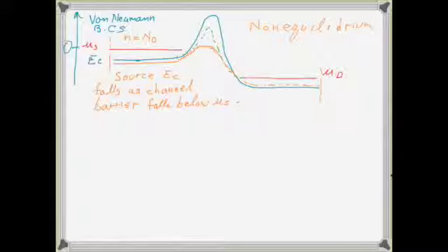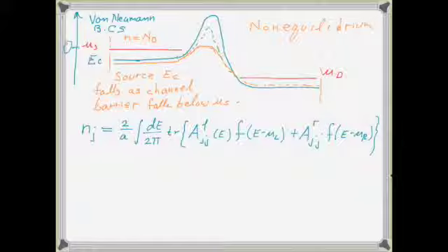To understand what happens, we need to go back and look at the equations that we use to get the charge density. That's the expression for the non-equilibrium charge density. For any normal FET, this difference here, q VDD, is at least 0.4 volts or more. Even 0.3 volts, it doesn't matter. At any rate, it's always at least on the order of 10 kT.